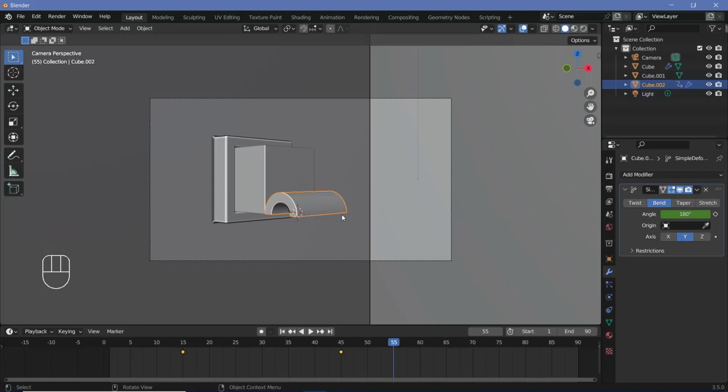and it started rolling. So there, you could change this from Bezier to linear, but we're actually going to play around with the keyframes and the speed later on. So I'm going to leave it as Bezier for now, after which I want this to also fall down. So at frame 45, I'm going to press I, location, rotation, scale, then maybe 1 second to fall out of frame.